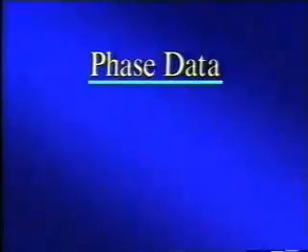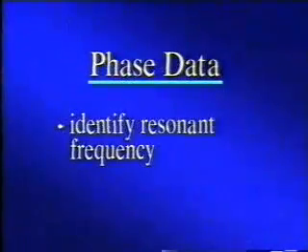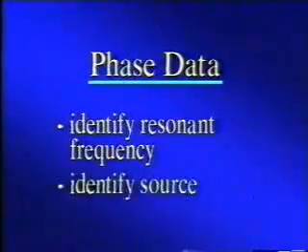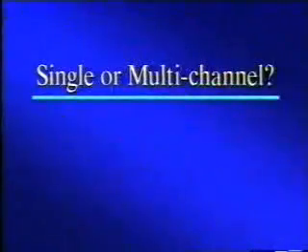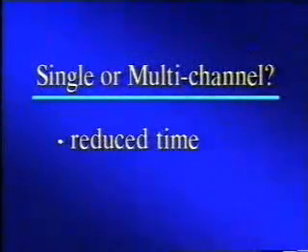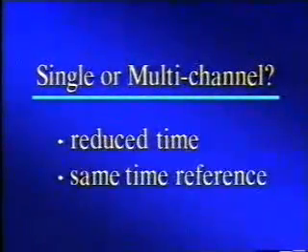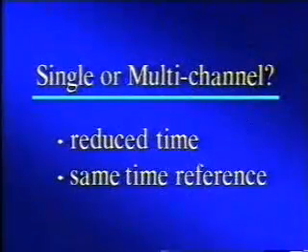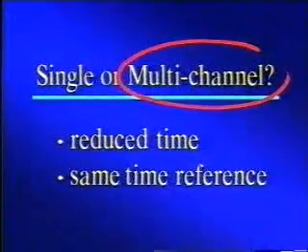The phase data provided the ability to identify the resonant frequency and the source of excitation. These measurements could have been taken with a single-channel analyzer. However, the reduced time to collect the data and the ability to have the same time reference for the comparisons made the multi-channel analyzer the tool of choice.